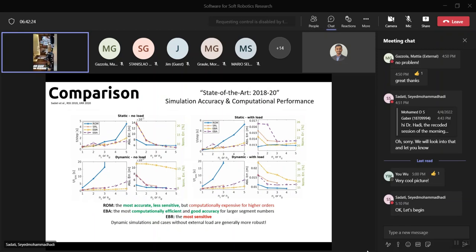Since then, there has been a wave of new reduced order modeling techniques in the community for sensing and control. People did it for backbone estimation, for geometry deformation estimation, for shape and force estimation, etc. Also, we looked at the sensitivity of these methods and noted that if you go for absolute states and rigid body kinematics, the large equations tend to be more numerically unstable.